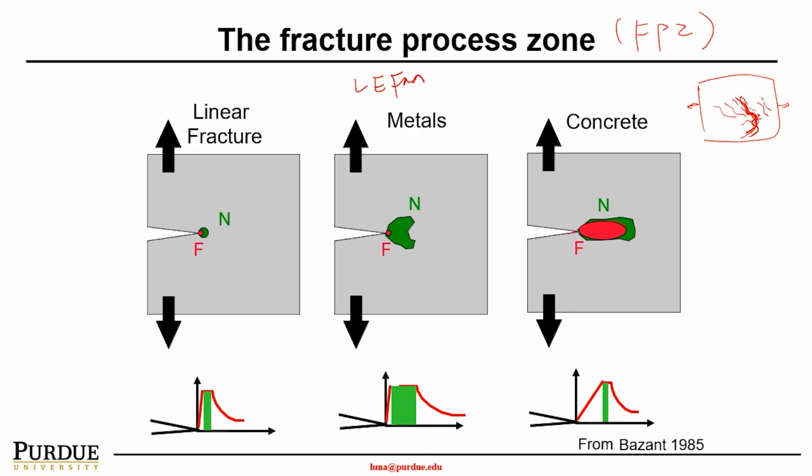So this is your cracked region, and this is not cracked region. So this fracture process zone becomes a bridging, and analysis of this zone deserves very special notice, because it's very helpful to predict the propagation of the crack and ultimate failure of the material such as concrete.